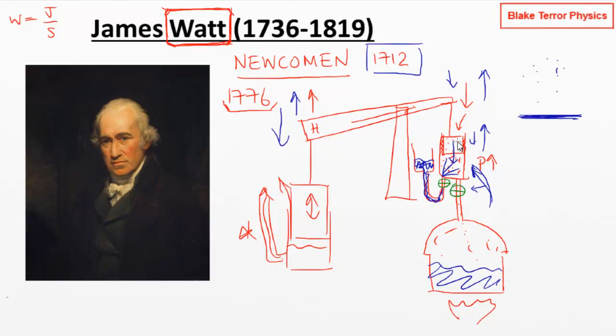But you can see one immediate inefficiency of this, that we're continually heating and cooling not just the gas, the steam that we've got inside the piston, but the whole piston itself. So we let the steam in, and you've got to do extra work because you've got to heat up all of the piston, and then the water comes in, it condenses the steam, but it also cools the piston, which we then need to reheat again.